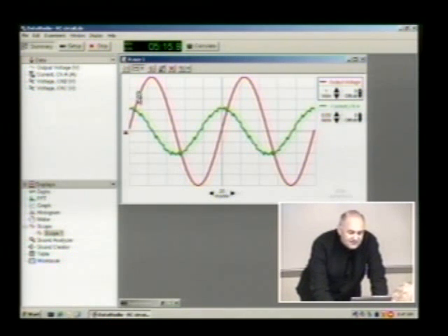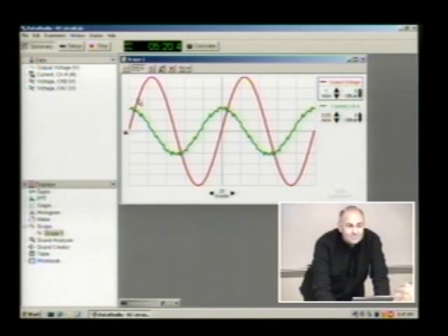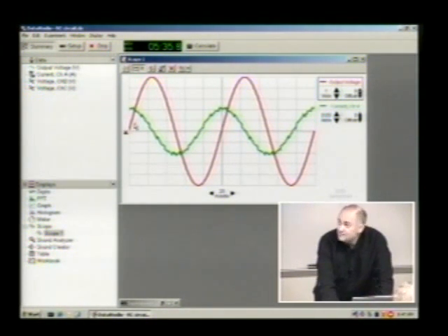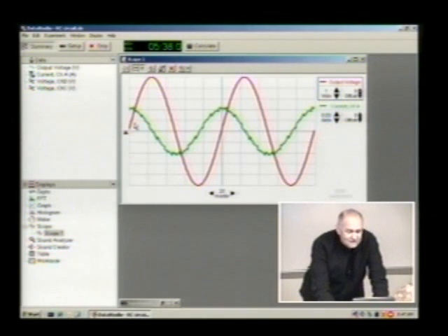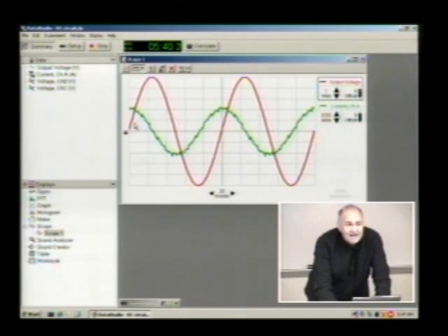Now over here, look at that. What is the derivative of voltage? Is it positive, negative, or 0? Positive. And current is positive. Now here we have 0. Is the derivative positive or negative? Negative. And we got a negative value. Now tell me where is the point that the function has the highest slope, which means that the derivative has the highest value.